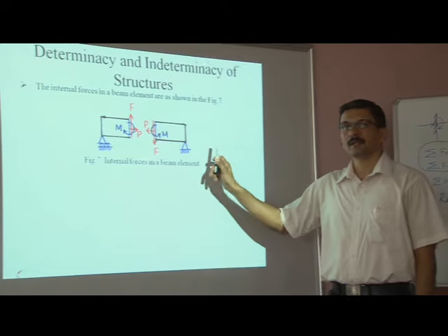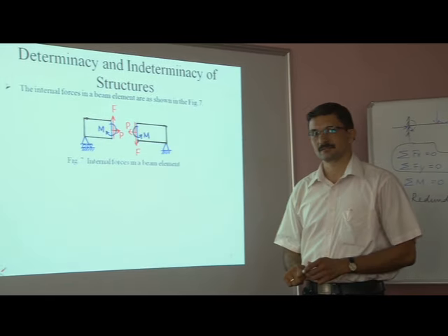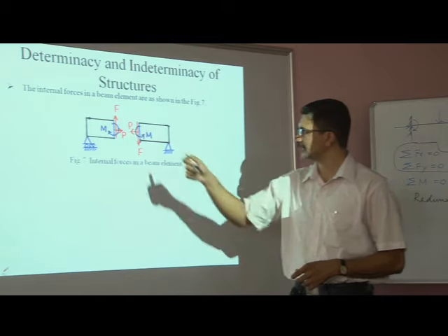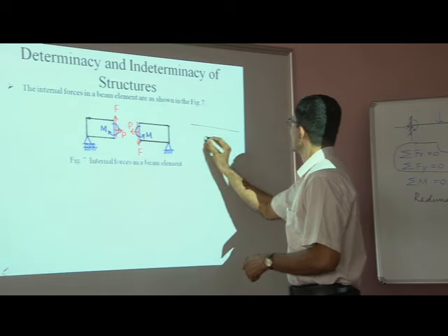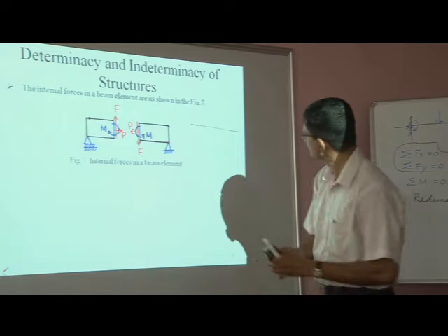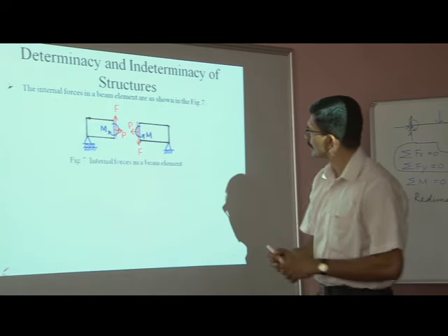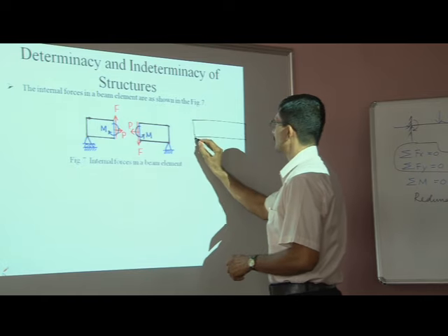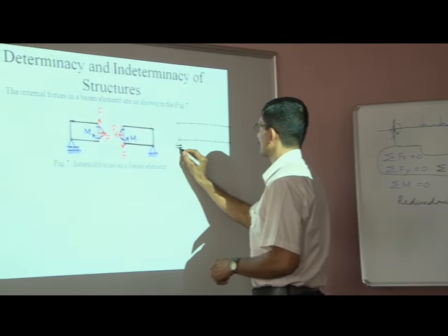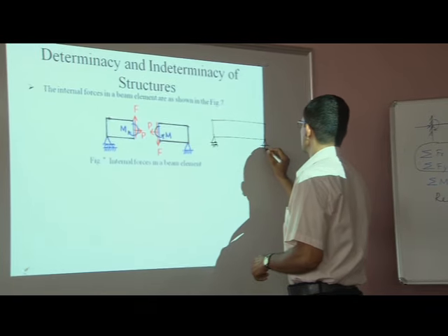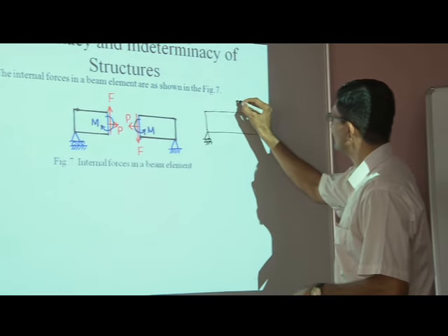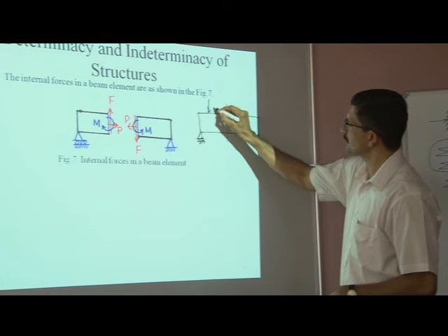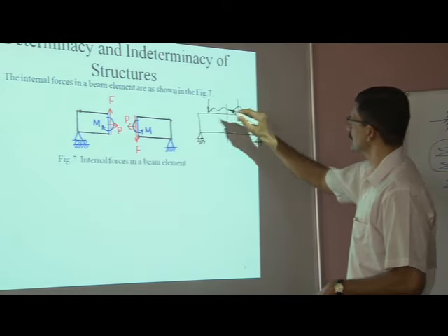Further, in case of a rigid jointed structure, say a beam, if you just make a cut in a beam like that, so that is a continuous beam. It was continuous initially like this. The beam is given 2 supports, one is the roller, other is a hinge at this end, and with a vertical plane I make a cut over here. I break that into 2 pieces. There are external forces, of course, in the beam, transverse forces, point loads and UDL.